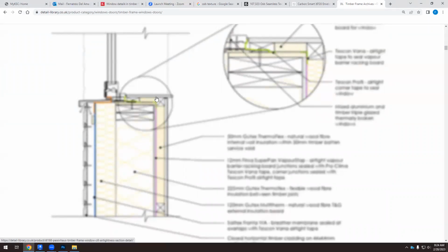We need something to. We need like a cap for this thermal insulation, and then we will move the internal finish up to this. And then we need something here to cover all that stuff. And then we need something to prevent water from entering. And that comes from below the window. So here we have a window detail. It looks like a triple glazing, but it's blurry and we can't see exactly the detail here. The window details are extremely complicated.